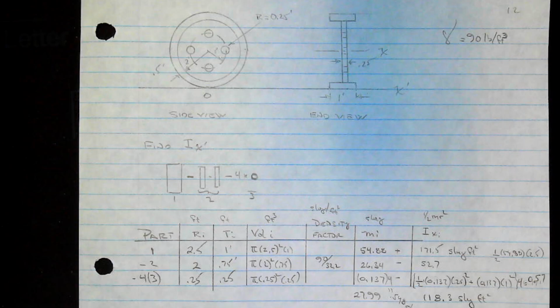It's not a constant torque being applied. It's as each cylinder fires. So the idea is that in between the cylinder hits, this just causes less change in the rotational speed. So that's the purpose of a flywheel, if you hadn't really thought of it before.